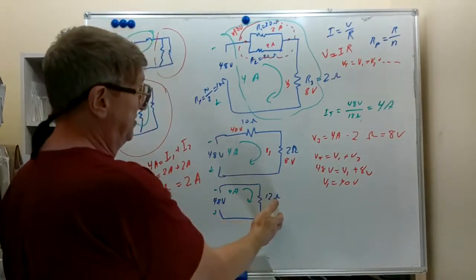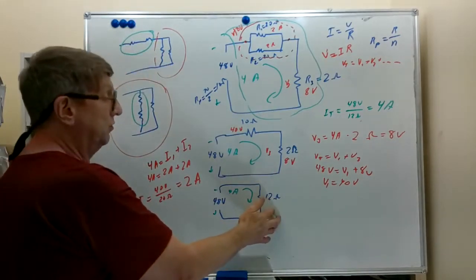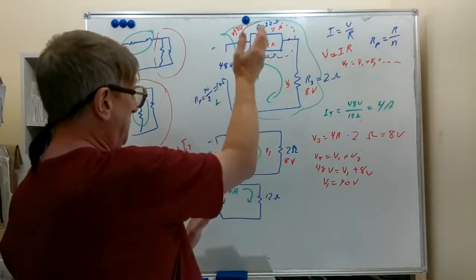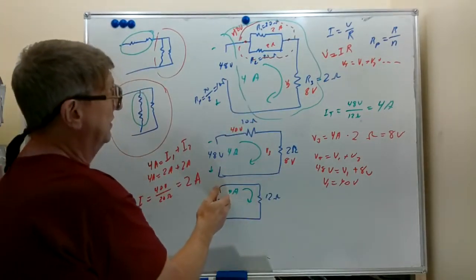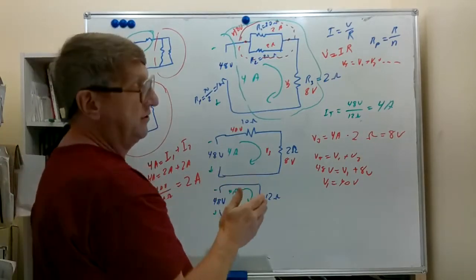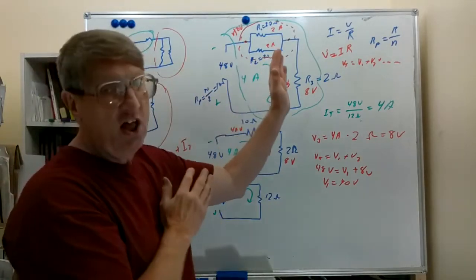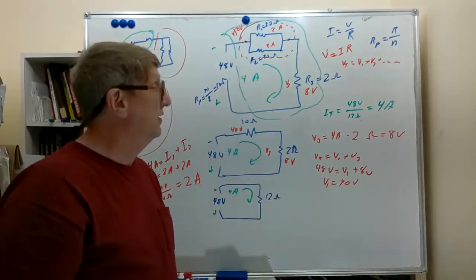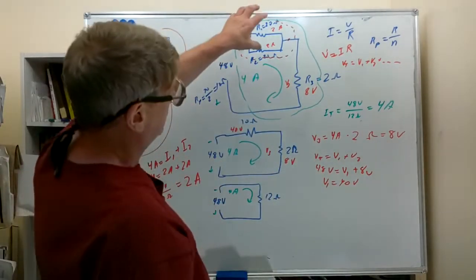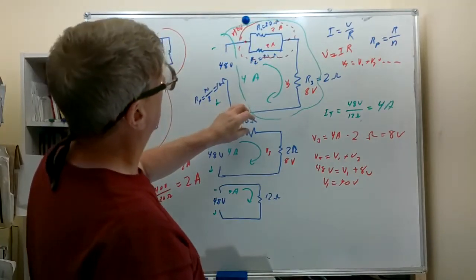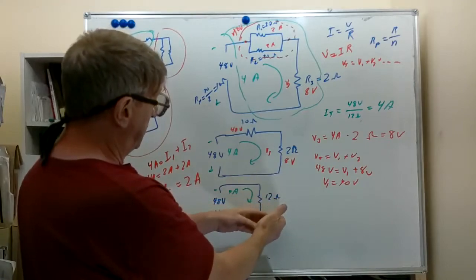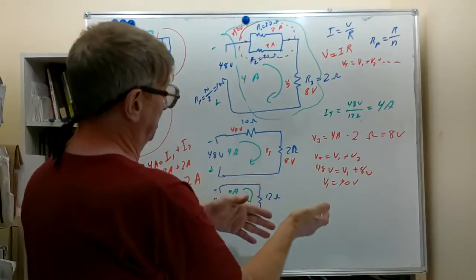That allowed us to find the total resistance. And again, we made sure we used all of the R when we calculated the current from the supply. Always make sure when you're solving a network like this that you don't miss some piece out there. We had this bank of parallel resistors. We made it into a single 10 ohm resistor. We combined the 10 and the 2 into 12, divided 48 by 12, got the 4 amps.